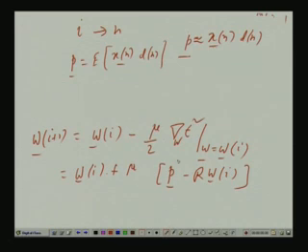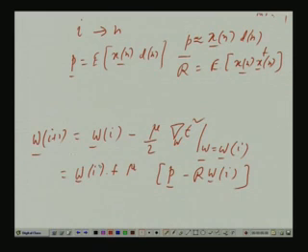Similarly, for R we should have x n into x n transpose plus x n minus 1 into x n minus 1 transpose plus many terms, and then add and divide by the number of terms to have a good estimate of power. But again, like above, I will be following a very weird path. I will take a very rough estimate, just x n x transpose n.